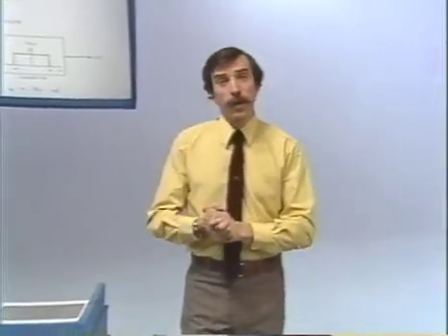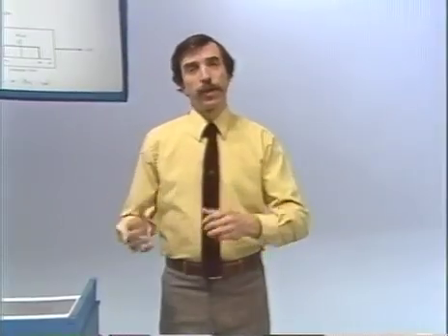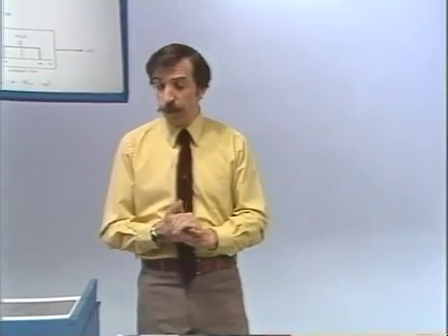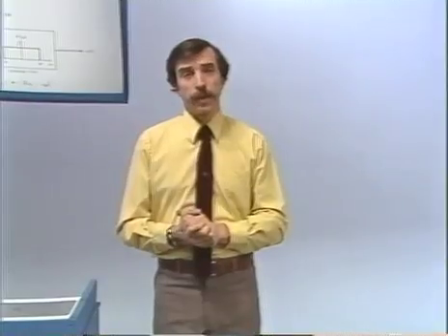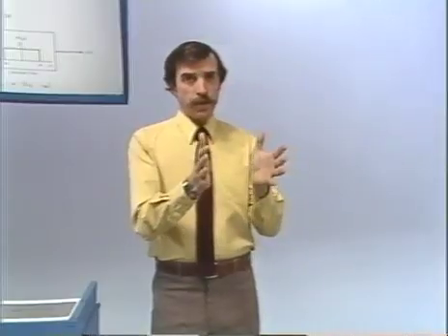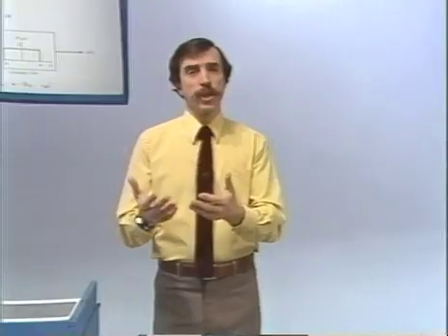And of course, one could ask, well, if you start with x of t and you want to get x of t back again, why bother going through all that? Why not just use x of t at the beginning and at the end? And obviously, there are lots of reasons, as I indicated before. And just to reiterate what they are, the notion often is that what you'd like to do is shift the signal into a different frequency band for transmission over some medium that is more matched to that frequency band than the frequency range of the original signal.